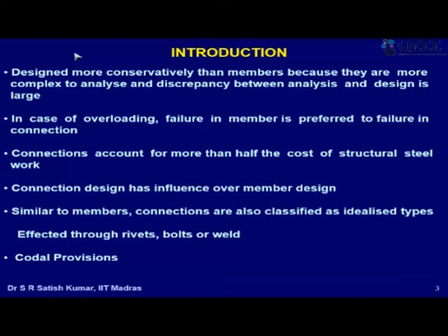You may draw something, like you may put bolts very close, but then the guy in the field will have difficulty putting a spanner and turning the bolts, tightening the bolts. So those problems also could come. So the code just gives you some guideline to help you make sure that you do a better design than what otherwise you would have done.